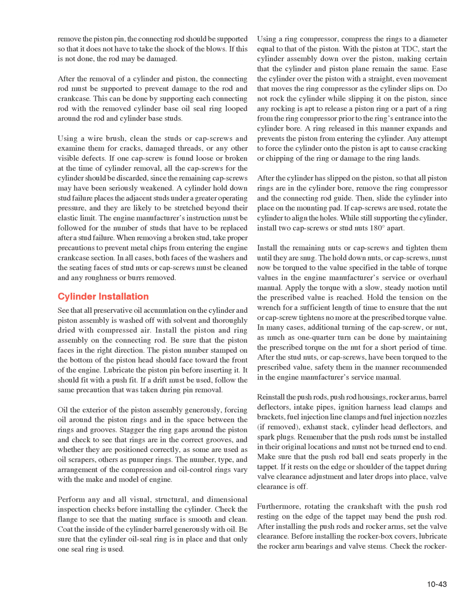Lubricate the piston pin before inserting it. It should fit with a push fit. If a drift must be used, follow the same precaution that was taken during pin removal. Oil the exterior of the piston assembly generously, forcing oil around the piston rings and in the space between the rings and grooves. Stagger the ring gaps around the piston and check to see that rings are in the correct grooves, and whether they are positioned correctly, as some are used as oil scrapers, others as pumper rings. The number, type, and arrangement of the compression and oil control rings vary with the make and model of engine.